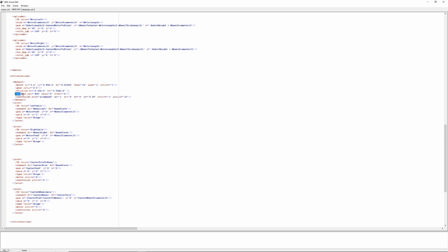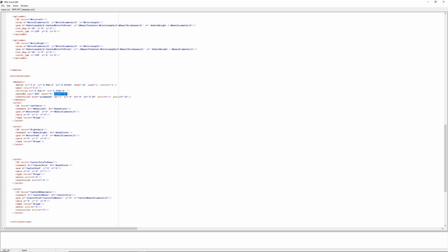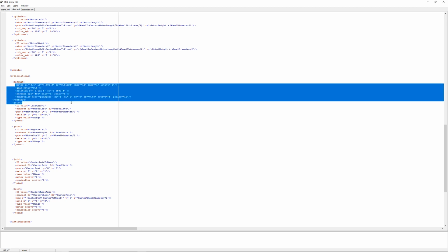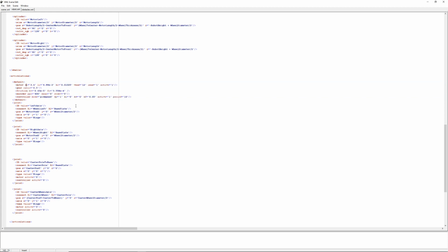You also have an encoder that you're gonna simulate that the right motor has an encoder that has 400 pulses per revolution, PPR, right here. And also the friction, the viscous friction, and all the elements for your calculations is right here. So you can change that. And also, even the standard deviation, you can enter here with a mean for all information regarding the right motor right here from your robot.